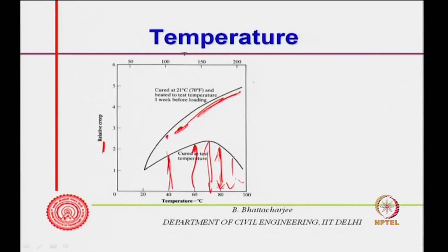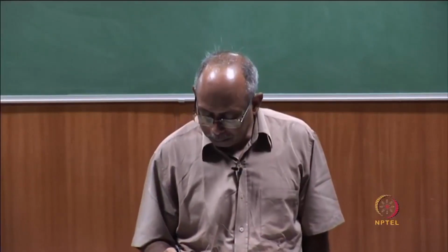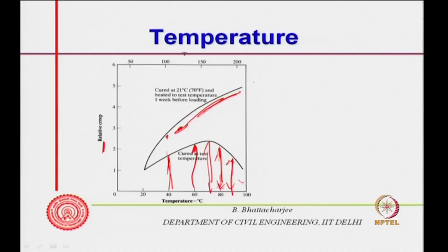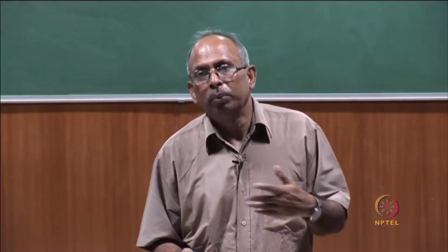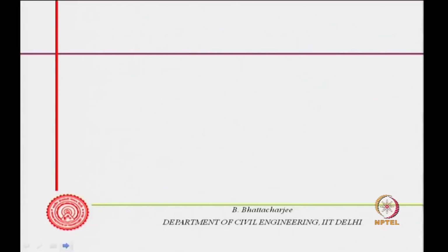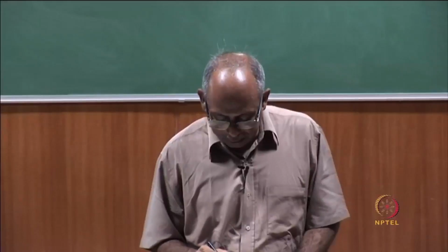So, that is what we are saying when you are actually removing some of the evaporable water during curing, because you are curing at 90 degrees centigrade and then applying the load. At this point the water has evaporated, but up to this point still there is an increase in the creep, but this creep is less than this, because some water has moved out. So, creep increases with temperature, that of course, we have seen, but then it has something to do with the movement of water, and that is what explains the situation,